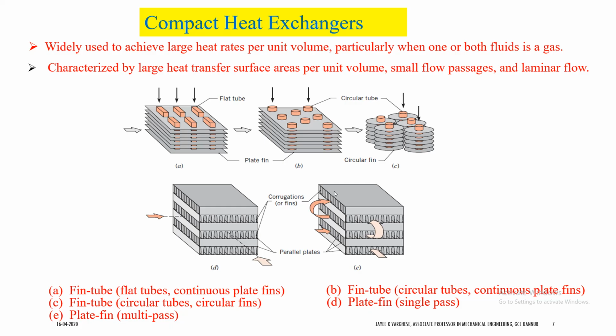Since we cannot play much on that, and also on the temperature difference between hot and cold fluids, there are many constraints on increasing that difference. So what is going to matter the most is the ratio of the area to the volume. If you have a small heat exchanger with a large contact surface area, we can increase the heat exchange, that is increasing A in this equation.